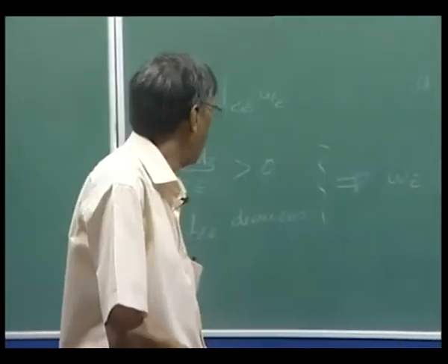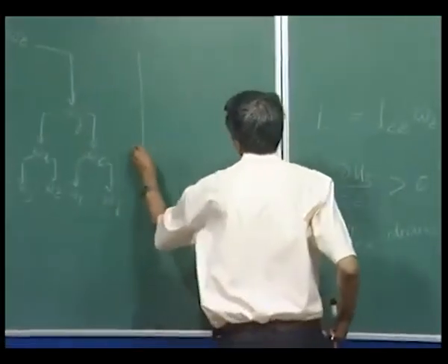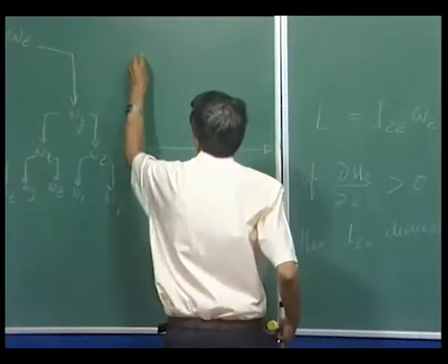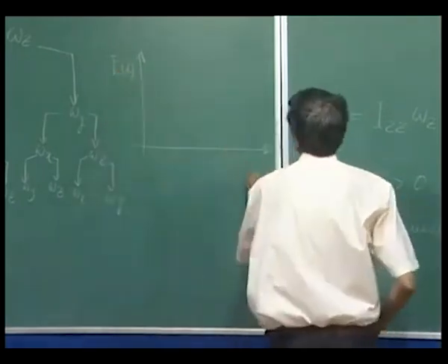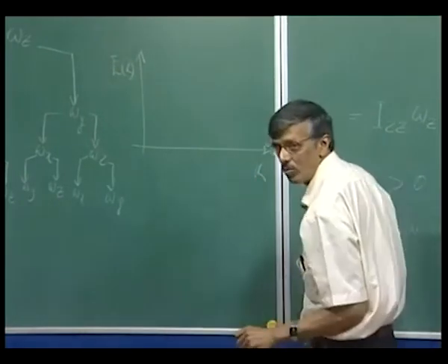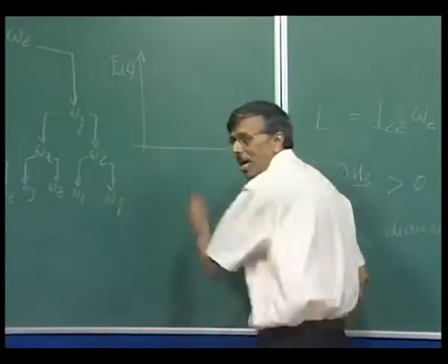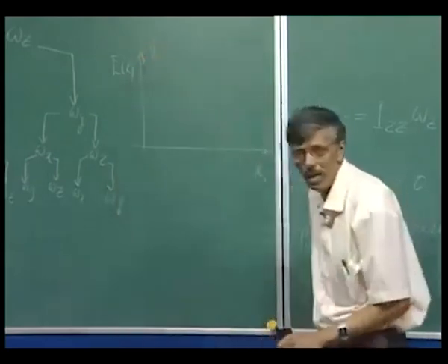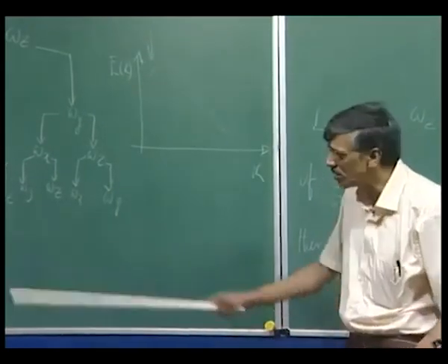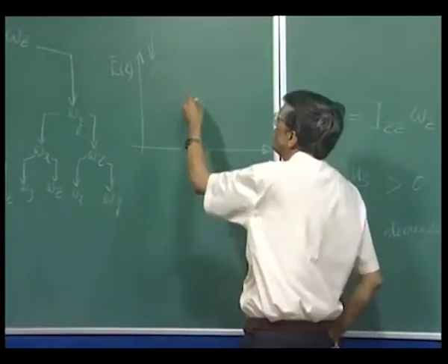That is what we have been talking about. We were talking about this idea for a long time, what E k does with k. If I talk about vortex stretching, this will essentially do that. If I pump in energy here at low k, because of the vortex stretching term, that energy has to shift to this.